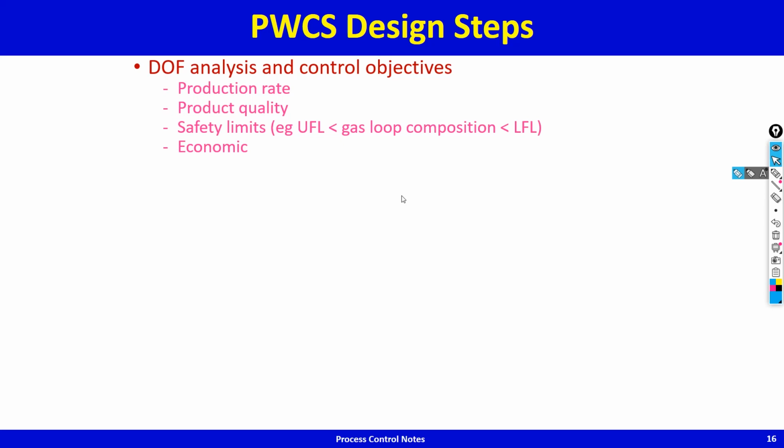Alternatively, what variable may I control by adjusting the reactor composition controller set point, to hold what magic variable constant such that my steam consumption in the reactor is minimum per kg product?